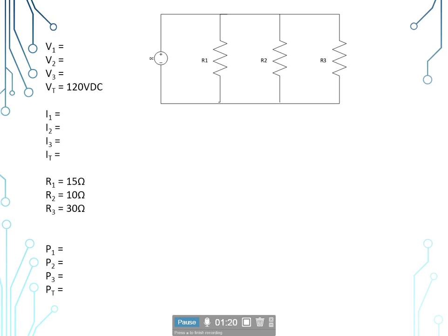Now to get started, we're going to have to find the total resistance, and for the total resistance we can use 3 different methods. The first one is resistors of equal value, where each branch would have to be exactly the same resistance, and you'd take the resistance of one branch and divide it by the number of branches. We can't use that here because we have 3 different values for our branch resistances.